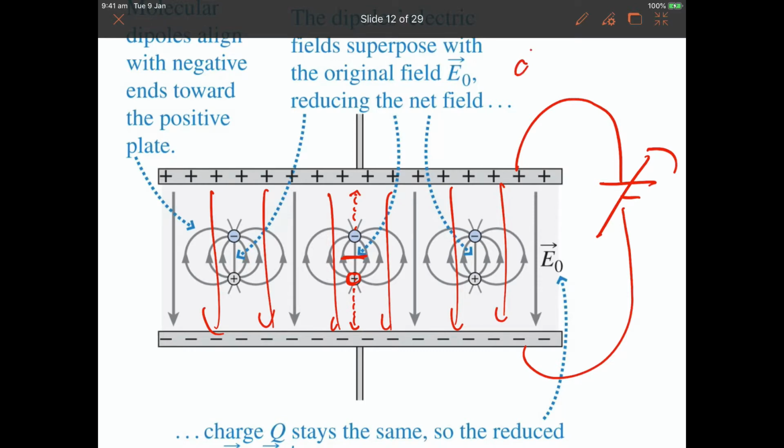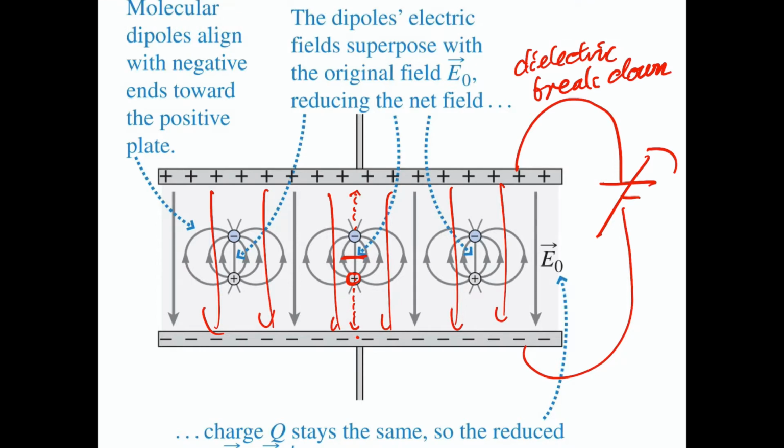The insulator, we call it, the dielectric breaks down. It means the molecule just tears apart by the electric field. And those positive ions will go to the negative side and you create a current. Now this happens not just for any material, including air. That's what lightning means. Later we'll look at the slide. So there's a maximum electric field you are allowed to supply.